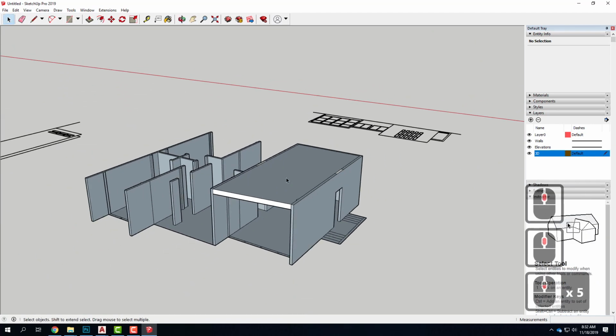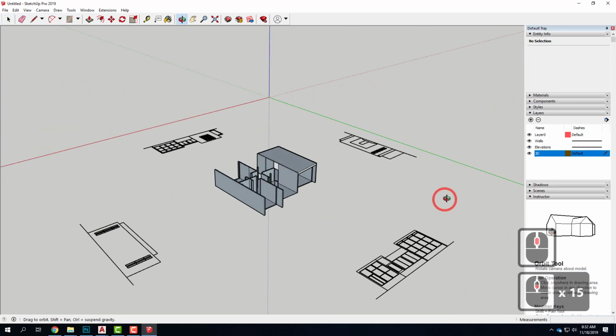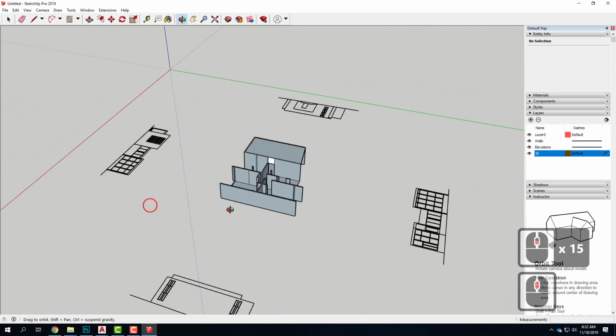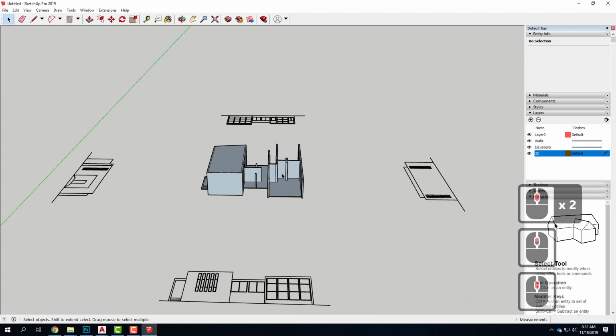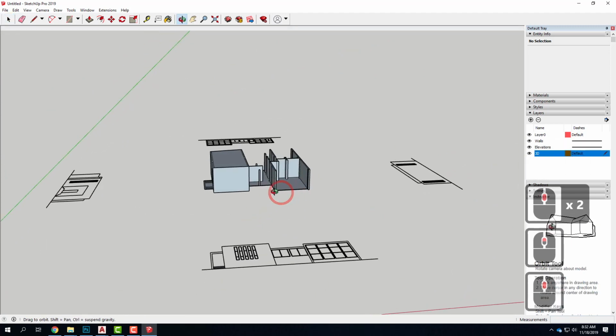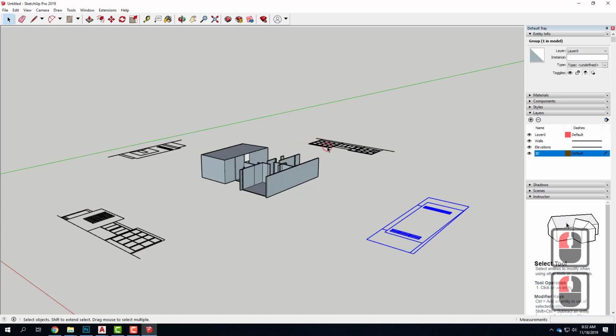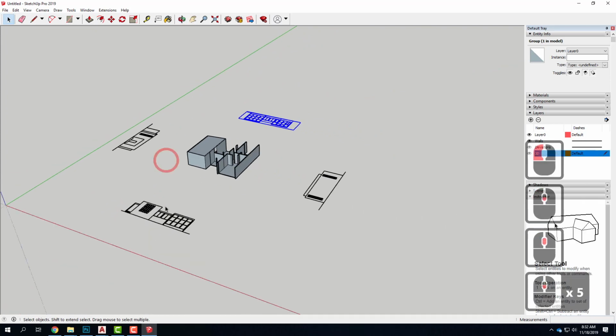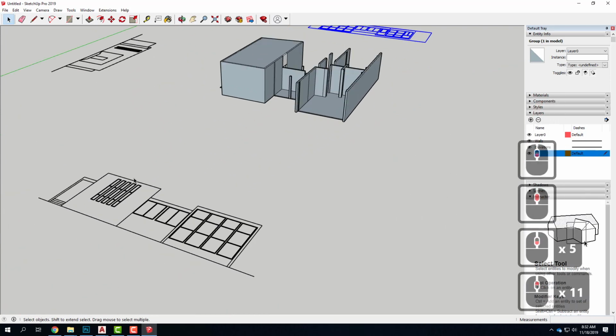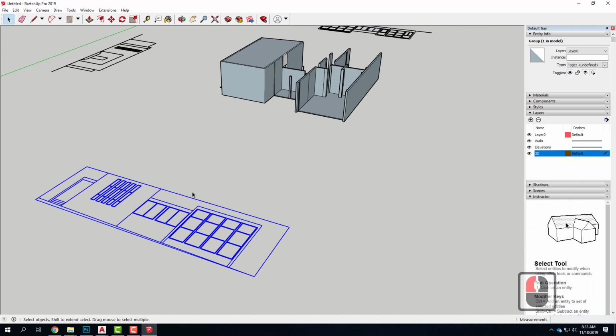If you have a sloped roof, sometimes it's useful to start using the elevations to your advantage. So let's think about the elevations for a second, and I'll use those to work on this side of the building. The elevations right now are laying flat on the ground. I need to get those to rotate up and position correctly so that I can use them to my advantage. Rotating in SketchUp works really easy when you have a three-dimensional object, not so easy when you have a flat two-dimensional object. So I'm going to give myself a little help.